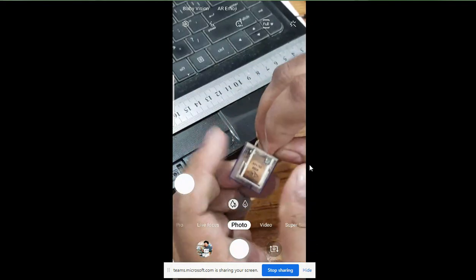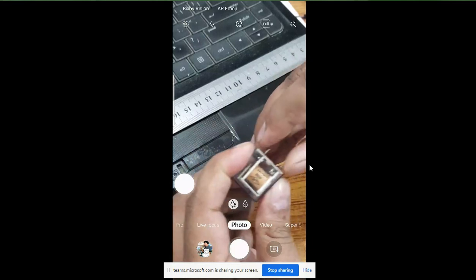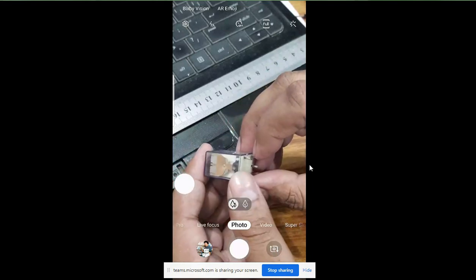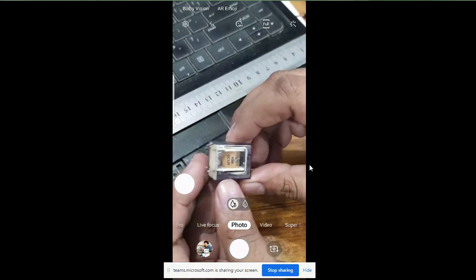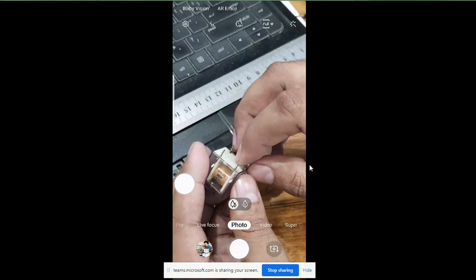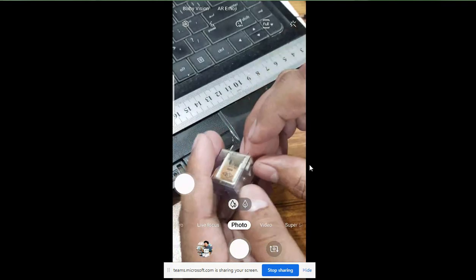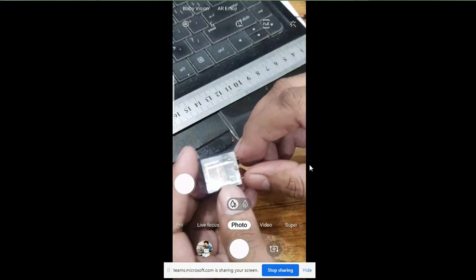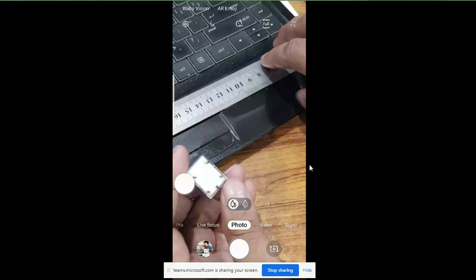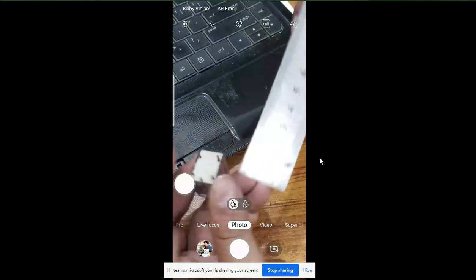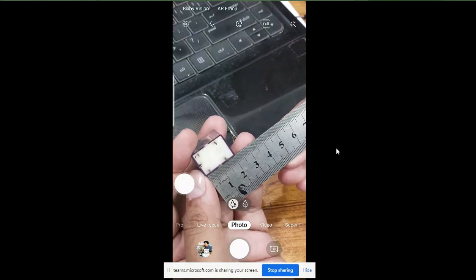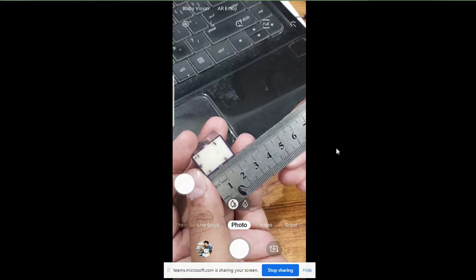Now first of all, whenever you have any item and you want to make a footprint of it, the first and foremost thing is that you need to know the dimensions of it. The PCB footprint of this relay maybe can be found on the internet, but sometimes the item is not there, so you have to make the footprint. The first thing you want to do is find out the practical physical parameters. Please note it down; I don't have my pen or pencil over here. So I'm just trying to find out the outer boundary of this one.